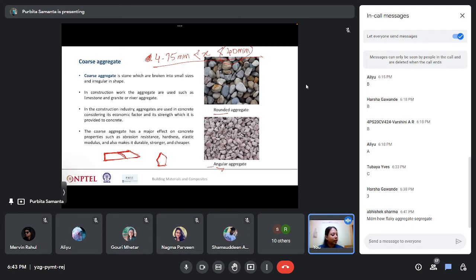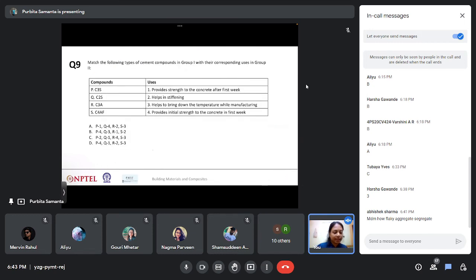Yes, as I was just talking about the different shapes of the aggregates. Depending upon the different shapes of the aggregate, we have seen that they are used in different places. So for bridges we use maybe particles which are near about 40 mm. There are different uses for aggregates which are 20 mm size, and then lesser diameter are used for clear cover. That also we have seen in our video lecture. So I hope this once again is clear.